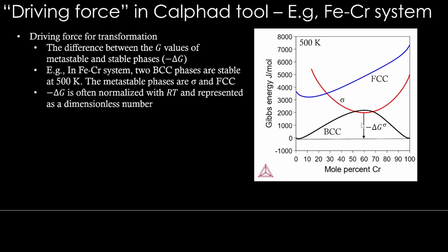And it is eventually going to change to two BCC phases of these compositions. The difference between this Gibbs energy and this Gibbs energy, that is the minus delta G for sigma, meaning sigma transforming to two BCC phases, that is the driving force.